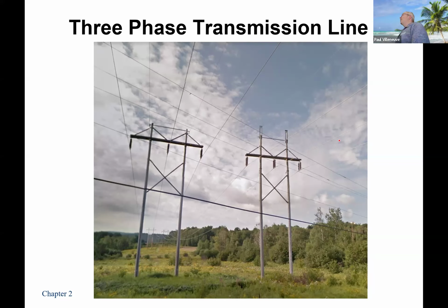So when you go down south or in more urban areas where you can't get straight lines because the land is too expensive, you've got to start running all different directions. They use a lot of steel poles because with a steel pole, you have to design a foundation, and that steel structure is designed to handle all the forces at the top. So steel poles don't use guy wires. They just use a bolted concrete foundation.